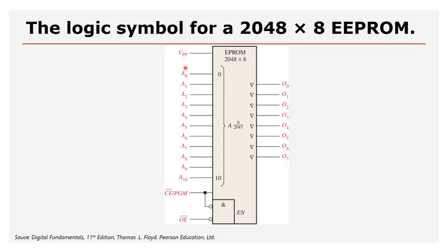So basically, in this specific device, we've still got the address bus, we've still got a data bus, and in this case the CE, chip enable line, and the output enable line, which is the read line. Normally, once this device is programmed, I will enable the device by putting a 0 on the chip enable pin, and it will activate this device.